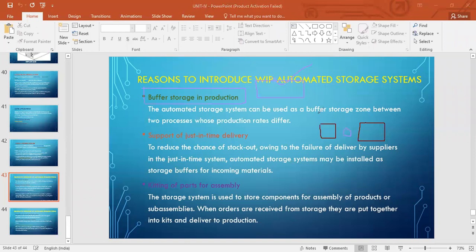Okay, so for example, this machine is taking too many hours to complete a product. So how will the parts wait here? And let's say this machine's production rate is high, so more and more units will pile up, isn't it? So then you have what is called blocking, because it cannot forward the completed work parts.